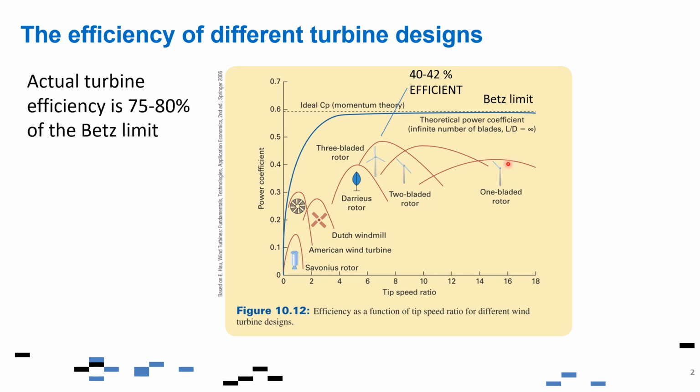more than 40%. But because of the design of only one blade turning around, you have to ensure that the tower and the foundation are strong enough, because this will also result in some form of imbalance when it is rotating around. So there's an issue with that. And a similar thing for the two-bladed design. It's quite fast because there are only two blades. You can have a really high speed blade design.